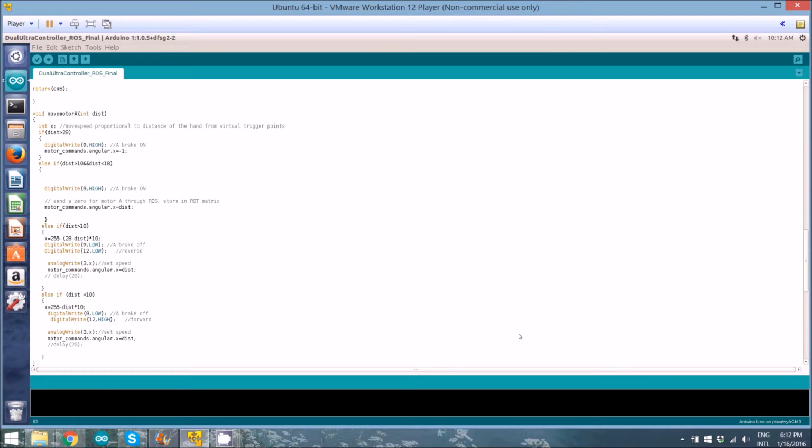So basically what happens is if you don't power on the buggy using an external power source and just connect it using a USB, whenever you run this piece of code with the movement functions not commented, and you are in the working distance, that is inside 28 centimeters as it's defined here, the buggy would sense it and try to move, but it doesn't have enough power.